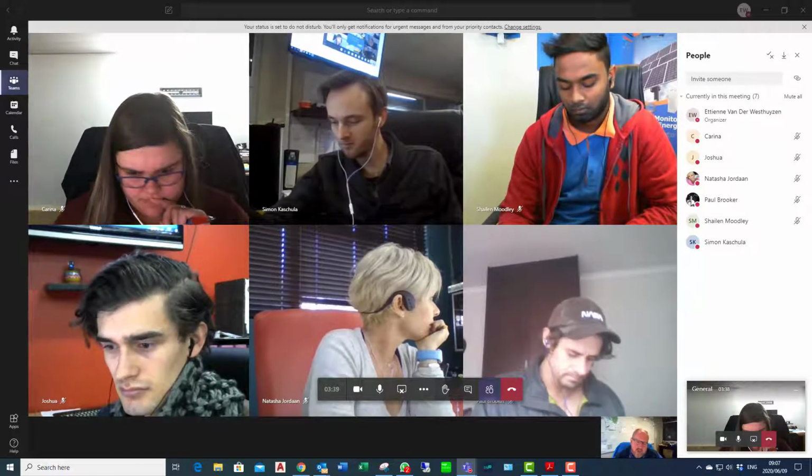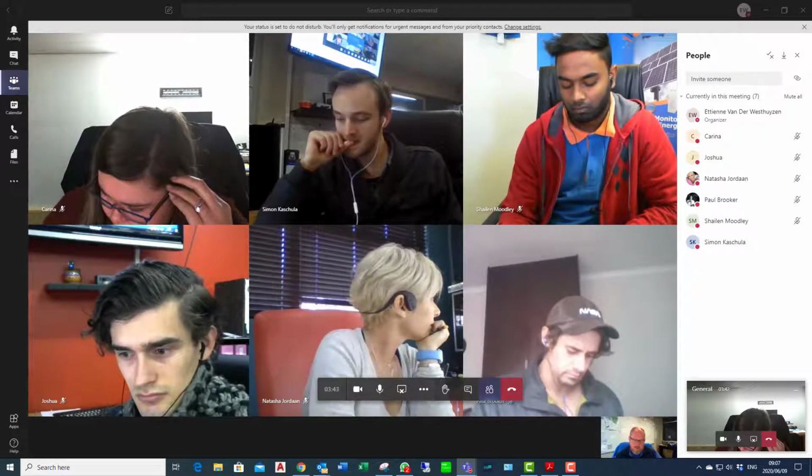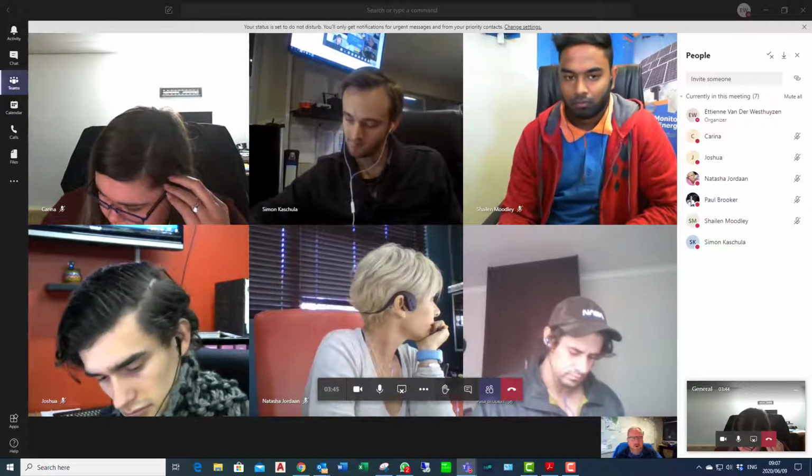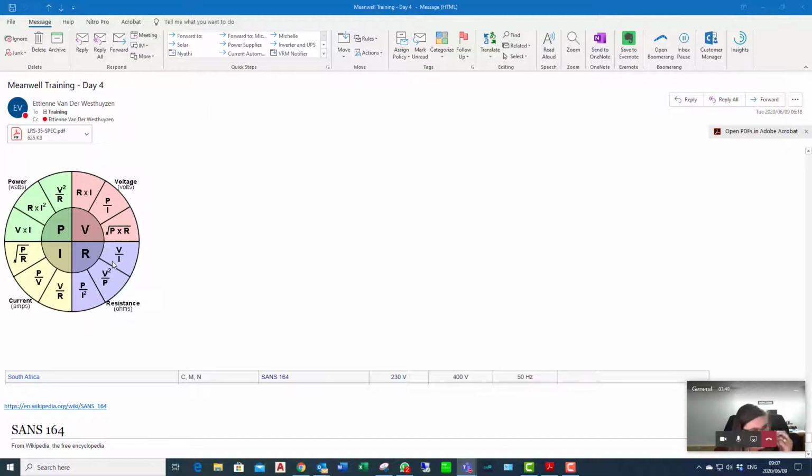Okay. So if we use a nominal voltage of, let's call it 240 volts, we go back to that little formula of ours, if you guys see my page here, P = VI. So I equals 35 divided by 240.